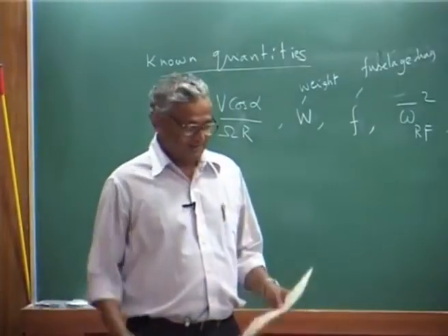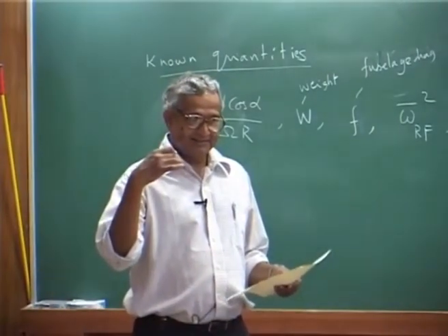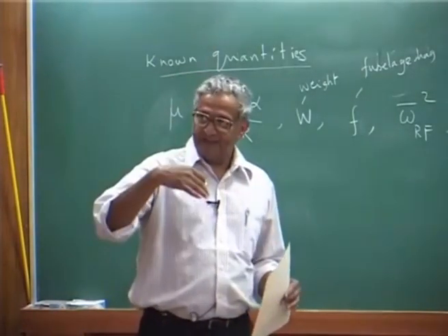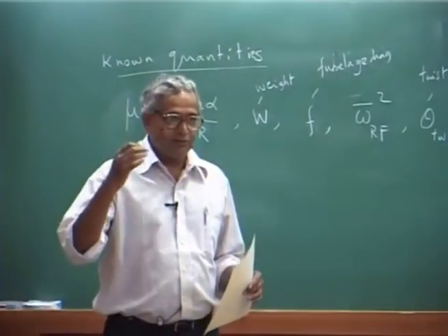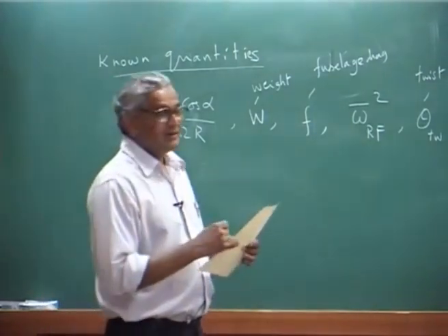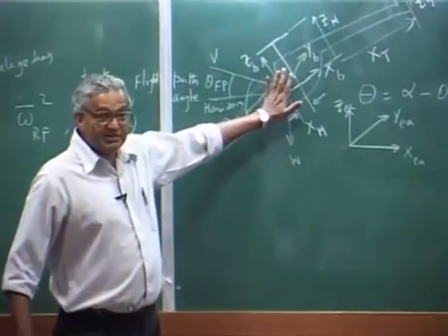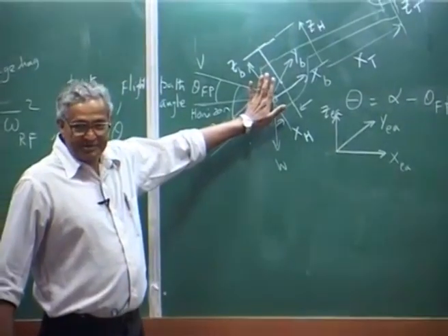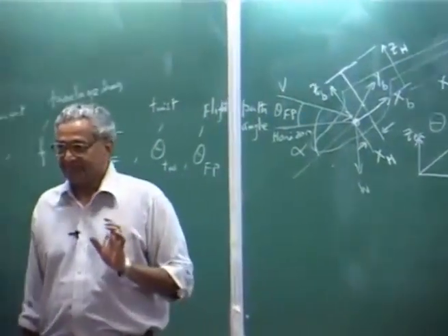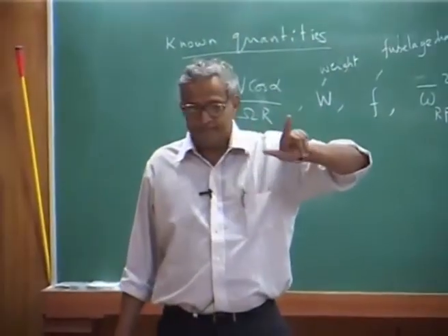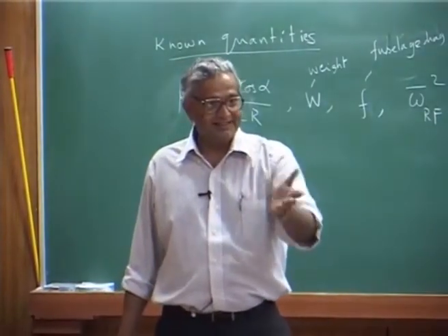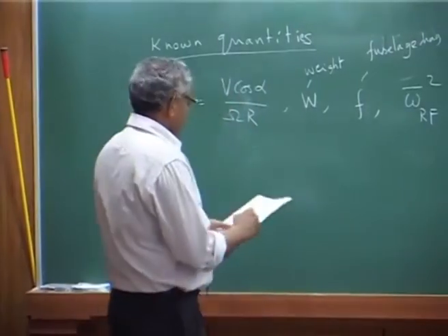First you rotate about x axis, that means roll, and then after the rotation of x you rotate about y axis, okay. So that you get the body axis system, you understand. From the earth axis you want to go to body axis. So the transformation sequence, you first say roll, then pitch.